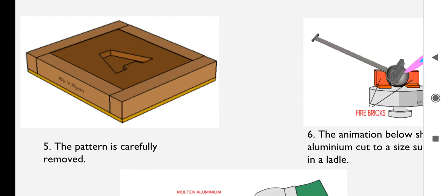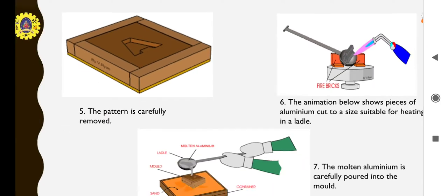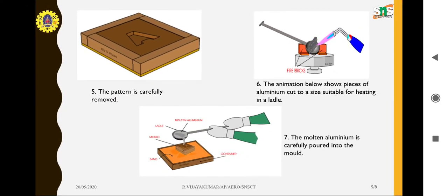And the second one is metal. Metal patterns are extensively used for casting because of their strength, accuracy, good dimensional stability, durability, and smooth surface. Many materials such as cast iron, brass, aluminum, etc., can be used as pattern materials. And plastics are also used as a pattern material because of their low weight, easier formability, good dimensional stability, smooth surface, and durability. The example is epoxy resin.